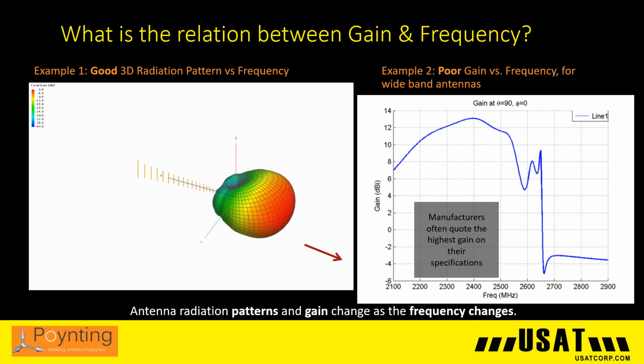In this example, the gain at 2100 MHz is 7 dBi, and at 2400 MHz it is 13 dBi. This is a big delta in such a short distance in frequency, and if the system is supposed to operate over both frequencies, you may have an issue in edge coverage situations. This confuses people to no end many times.